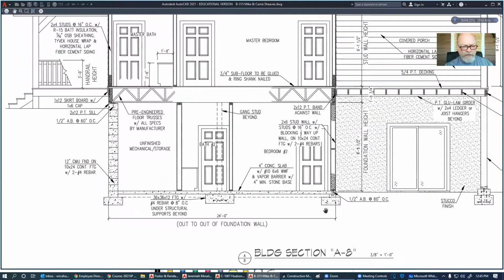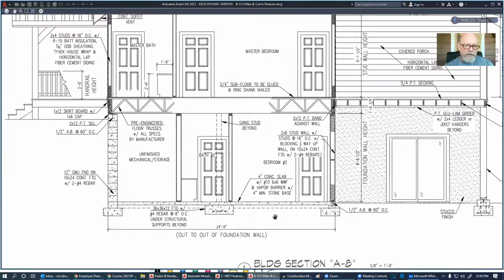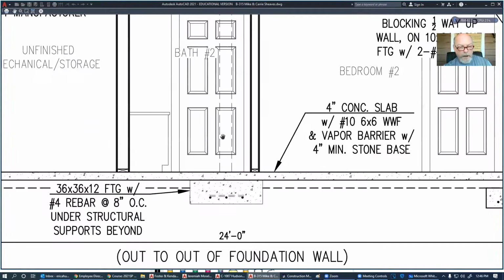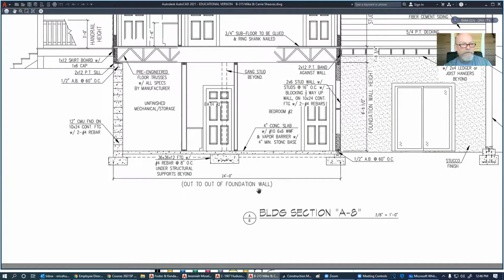Generally, the majority of that settling takes place within the first year. Depending on the weather, the climate, and any flooding, it may or may not settle any further after that. But that gives you an idea of that spread footing for a post, or what we call a pier footing.